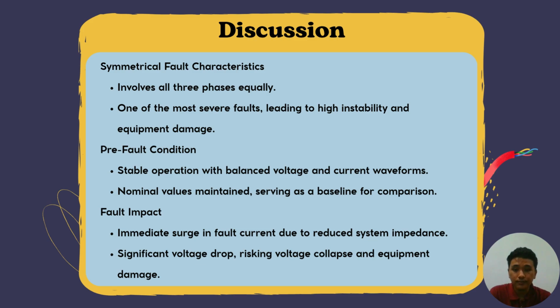For discussion, firstly we have our symmetrical fault characteristic, which is the three phases involved equally, and it is one of the most severe faults, leading to high instability and also equipment damage. Secondly, the pre-fault condition has a stable operation and balanced voltage and also current, being the baseline for our comparison for the simulation. The fault impact is an immediate surge of fault current due to the reduced system impedance and also a significant voltage drop.